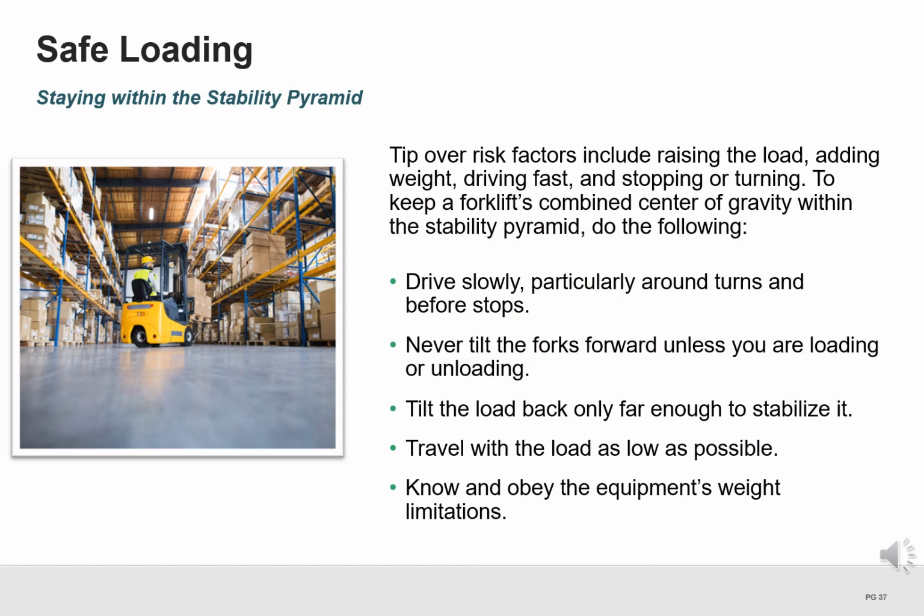Several factors can increase the risk of a tip over, including raising the load too high, adding excessive weight, driving too fast, and sudden stops or turns. To keep the forklift's center of gravity within the stability pyramid, always operate with control. Drive slowly, especially when turning or coming to a stop.